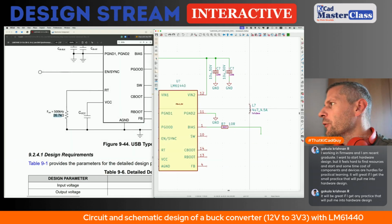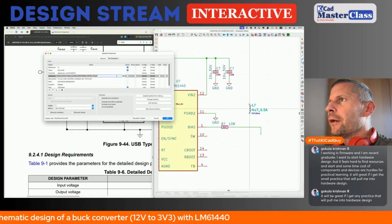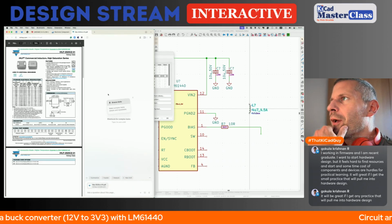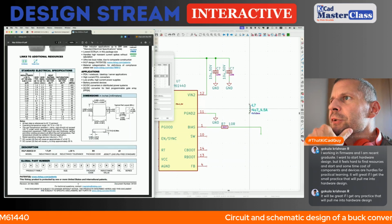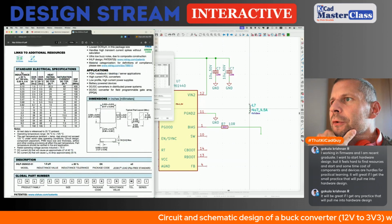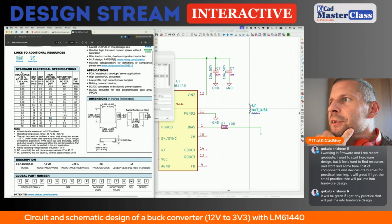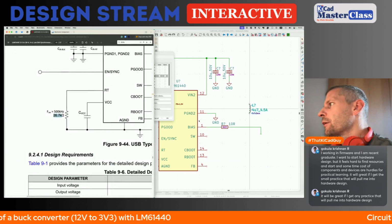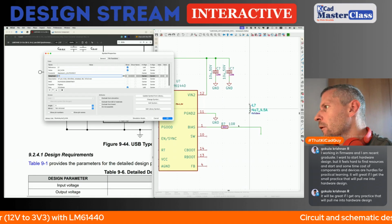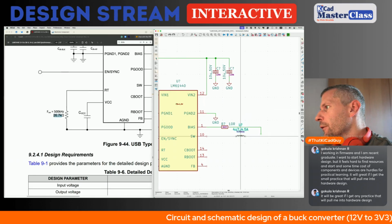This one looks good because there is a note about 8 amps saturation current. So let's check this table. 4.7, current saturation is 10 amps. It's fine. This is our inductor.